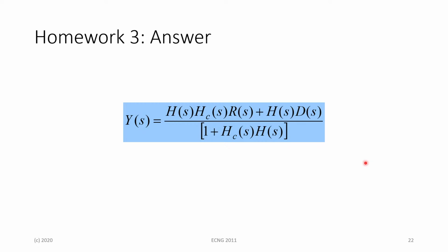Alright, so that basically brings us to the end of our block diagram simplification lecture. Basically what we saw is that the general strategy is to get feedback systems or feed-forward systems where we can eliminate those summation junctions one by one. And in order to do that, we need to employ the 4 techniques that we saw in today's lecture, being moving the takeoff points left to right and right to left, as well as moving the summation junctions from left to right and right to left accordingly.